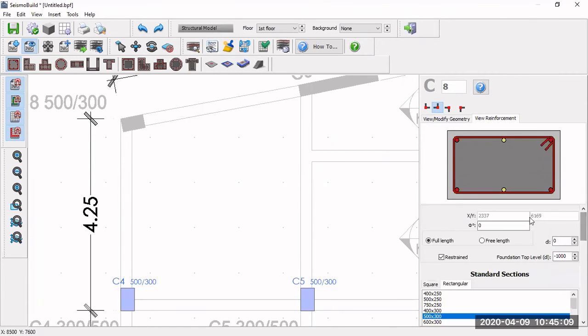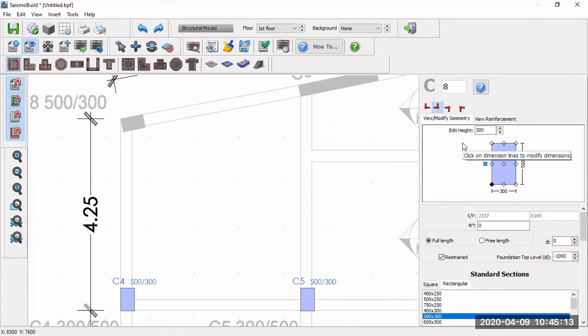All right. Okay, the way we're going to do the insertion point is, you notice that this column is inclined. So we're going to change our orientation to this corner. All right, and then we put our insertion point here in this angle. The angle will be based on the rotation point. So in this case here, I already worked out the angle is about 11 degrees. So I type 11 degrees.